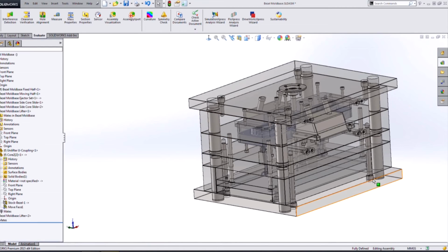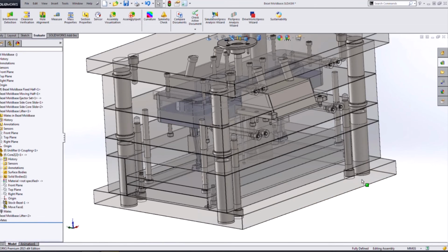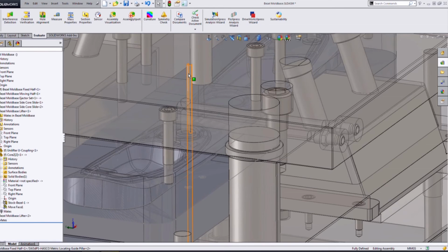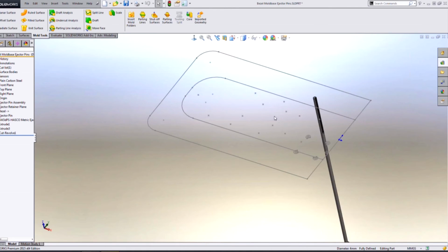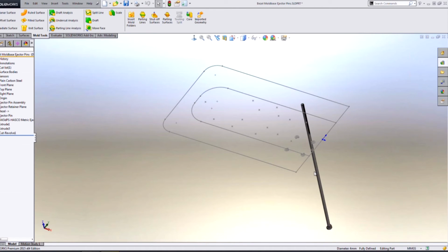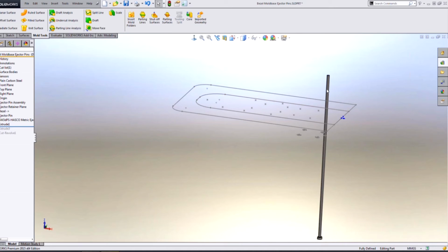And let's go ahead and open those ejector pins now. So we'll zoom in here, grab that ejector pin, and open the part. Now what we see is that the sketches that we need are already in here because this part was originally created in context. The only thing that we're going to do is roll this back a little bit and bring in some surfaces that we can use to help trim the tops of these pins back so that we have them flush with the actual mold shape.